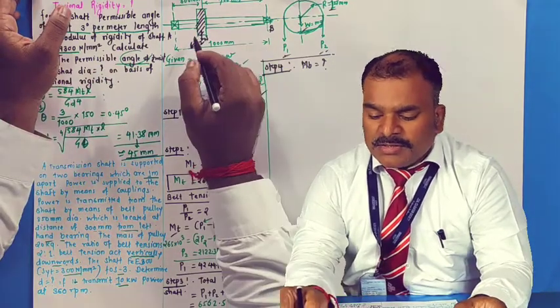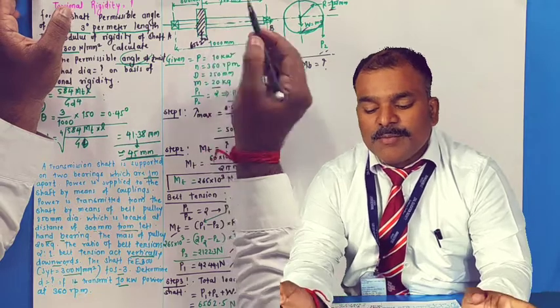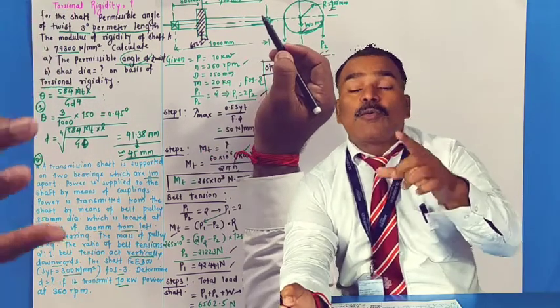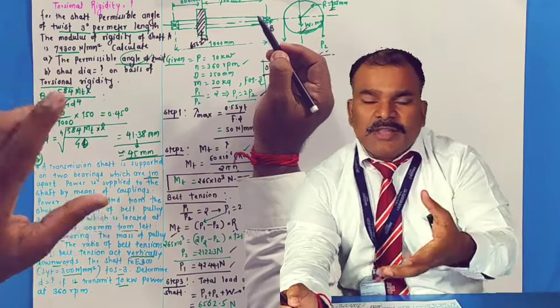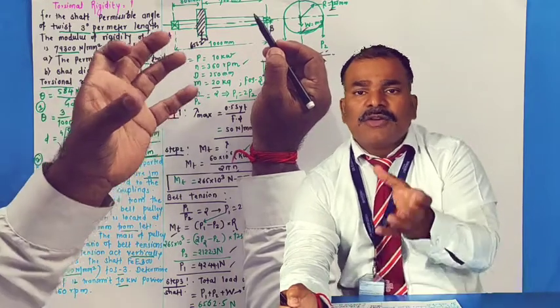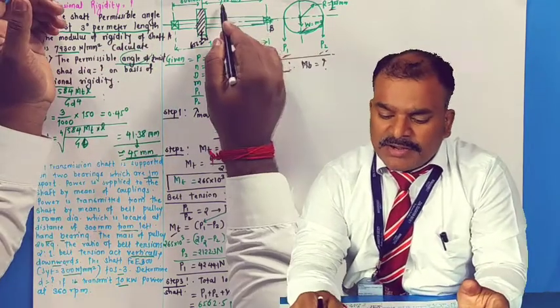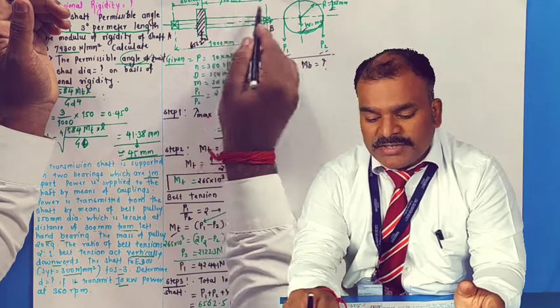But in case of the shaft with respect to bearing B, it is having 700 mm distance. So bending will occur only when the distance is more, correct? At a short distance bending will be there, but it requires more load. So right now we'll have to calculate the bending moment, that is, 700 mm is the distance. So I will have to take a distance of 700.